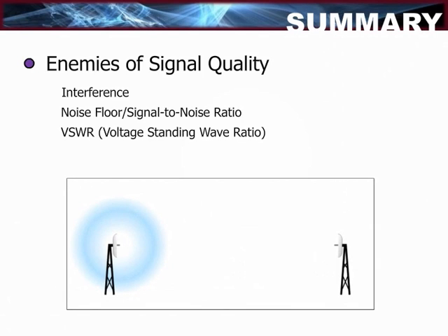Interference can stem from many different external sources. The deployment area of an RF system should be scanned appropriately before deployment so that clean channels can be identified. Recall that interference on either end of an RF link can affect the link as a whole.